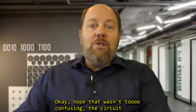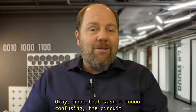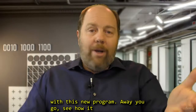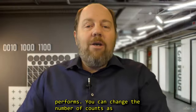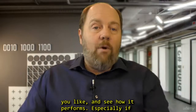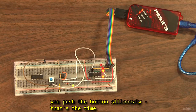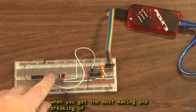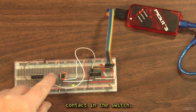Okay, I hope that wasn't too confusing. The circuit is already built. You just need to flash your PIC with this new program. Away you go. See how it performs. You can change the number of counts as you like and see how it performs. Especially if you push the button slowly, that's the time when you get the most making and breaking of the contact in the switch.